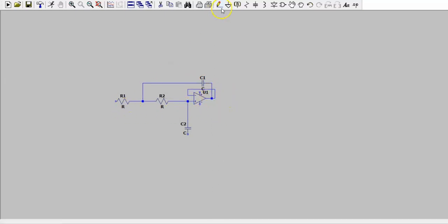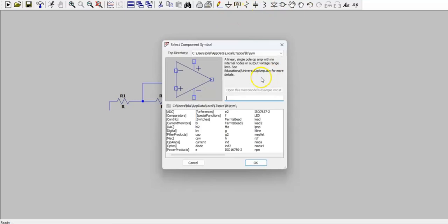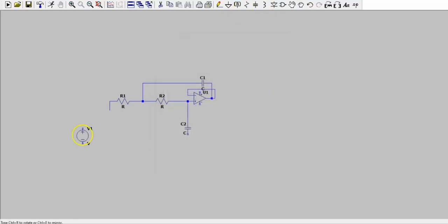Okay, and then we're going to put over here a voltage source and pass a step through that. So if you just get voltage, so one there. Then we're going to ground the two, the capacitor and the voltage source. So ground there and the ground there.